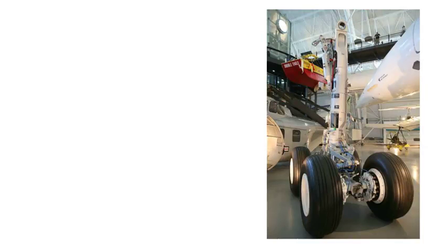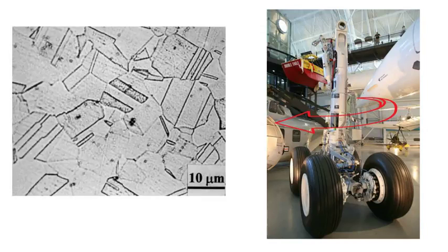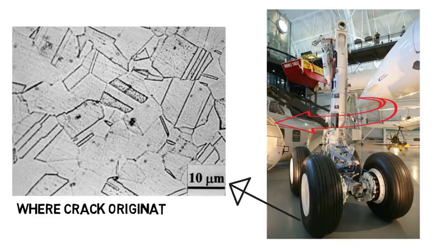But not shown here, the landing gear had a huge crack around it which almost broke it during landing. So he had to use a microscope and analyze the microstructure of the landing gear. This is a micrometer scale picture but tells us a lot. At this scale you can actually see where the crack originated from and how it physically propagated through the structure. The crack isn't shown here, but you'll learn how to analyze these in school.